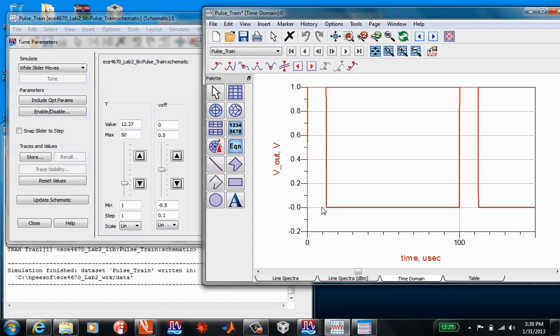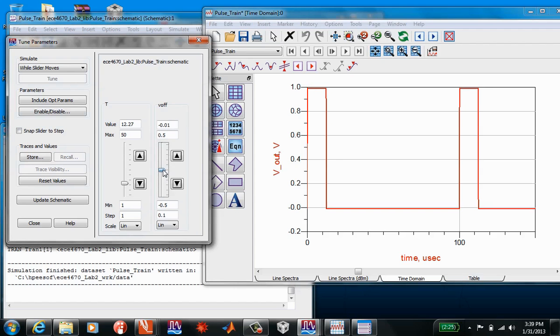So what should I do if I wanted to make this waveform, this DC component, go to 0? I should be able to slide it down, say like that. So if the area of this piece above 0 is equal to the total area of the negative period, that will make the average value go to 0, right? Remember that?